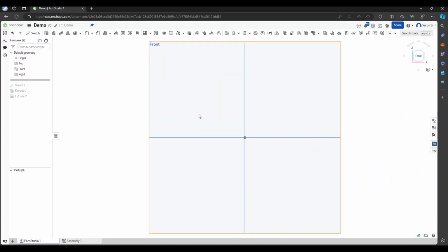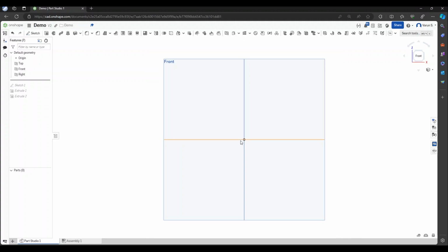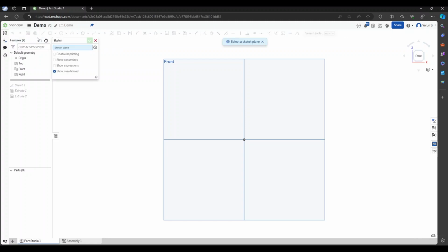And so we just want to make a sphere here. And so to do that, we're going to use the Revolve tool. And what that entails is a face or sketch region to revolve and a revolve axis. And so if you can't visualize how this is going to work out, that's fine. Just follow along with me. You'll see how it works.